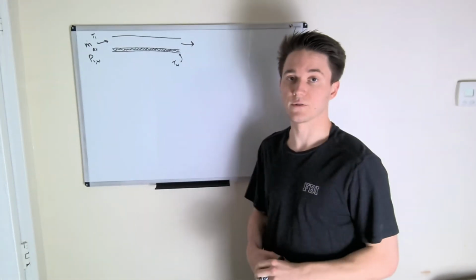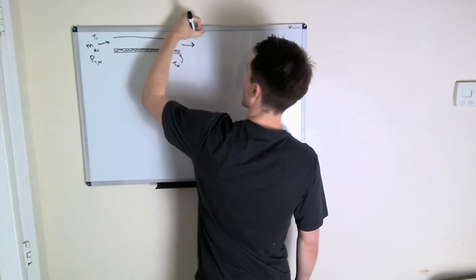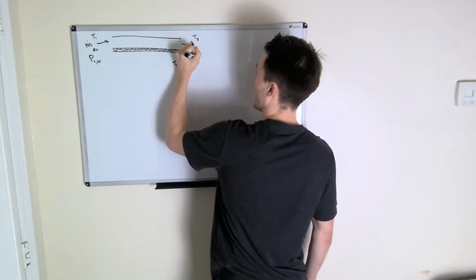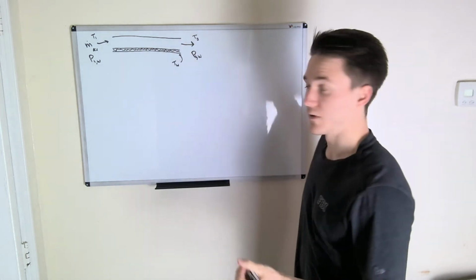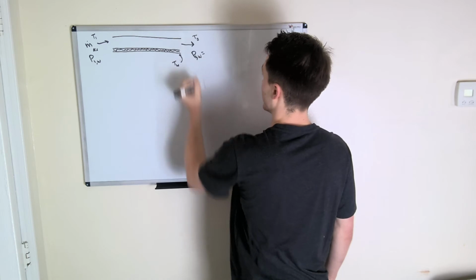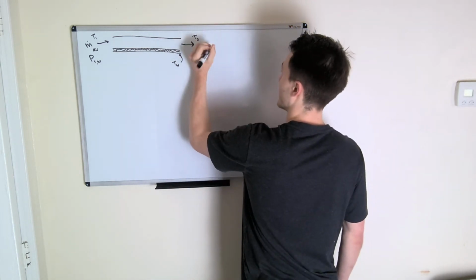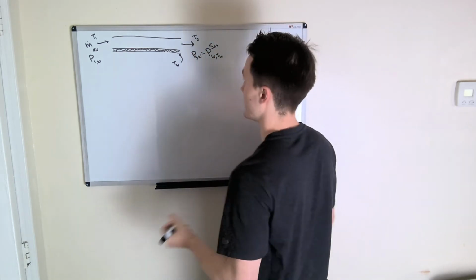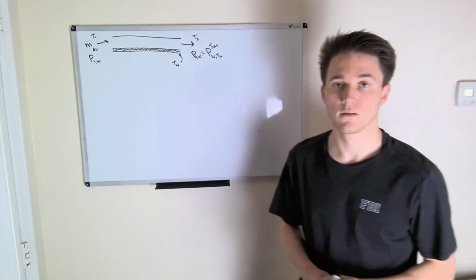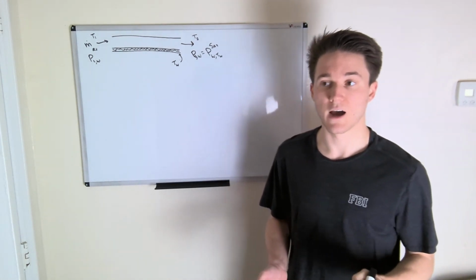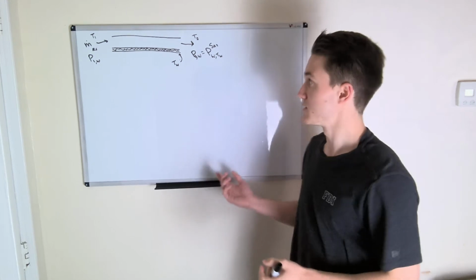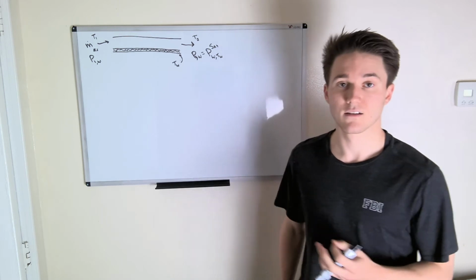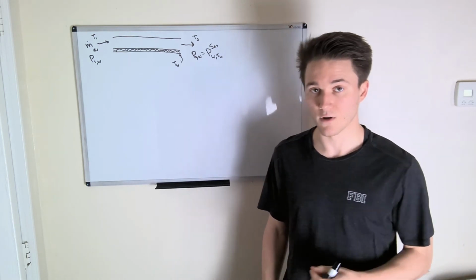Then in the outlet stream, we have our outlet temperature and our outlet partial pressure of the air. But this partial pressure of the water vapor in the air is equal to the saturation pressure of water vapor at TW. And so now we want to make our energy balance. Since this tube is at steady state, our enthalpy in is going to equal our enthalpy out.